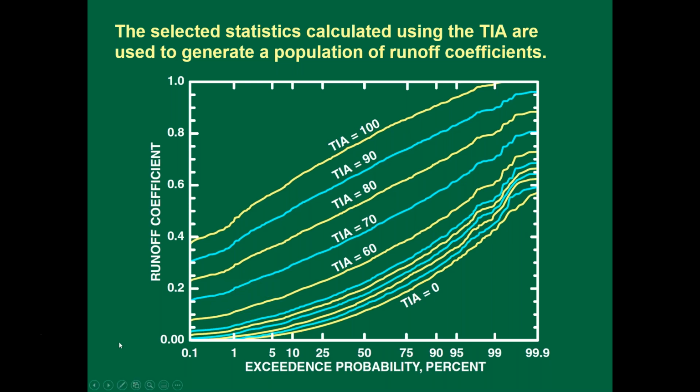So this graph shows one stochastic realization. So we ran all the same values, but just with different imperviousness. However, you're not going to get these exact values at your site, but you're going to get something similar if you just copied the analysis and ran SELDM and varied the imperviousness as it goes up.